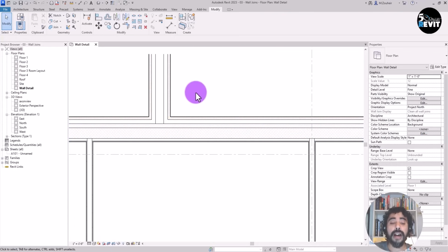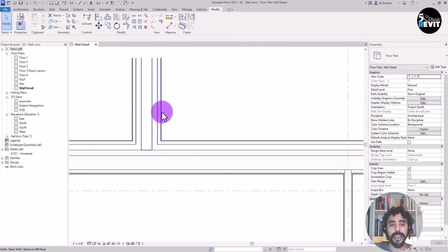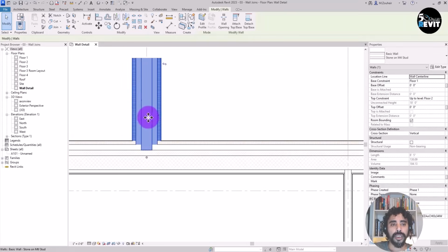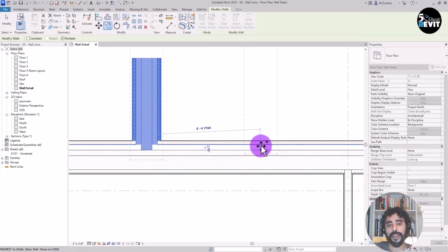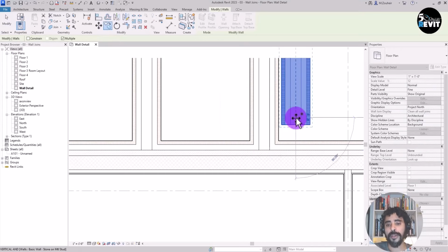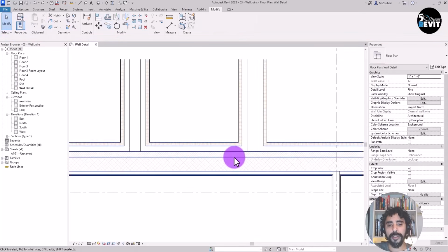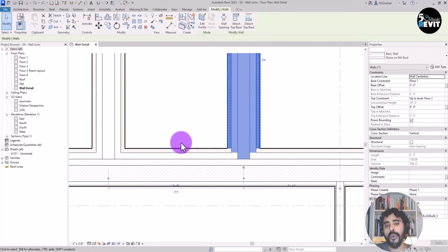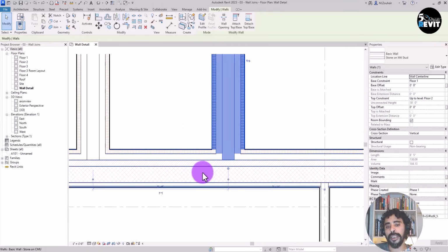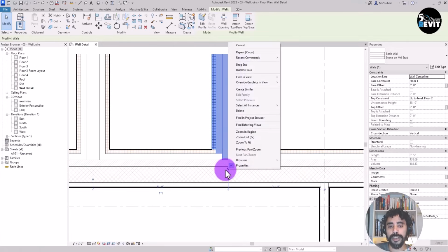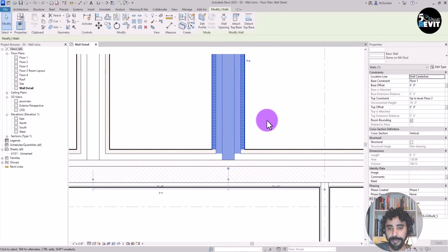And we can have another case if I select the wall like that and copy from here to here, for example. Now, Control Z, click on modify. Now it's okay. If the construction is already there for this external wall and then comes this wall, I want to have this junction between layers. For example, right click on the wall and choose disallow join, like that.